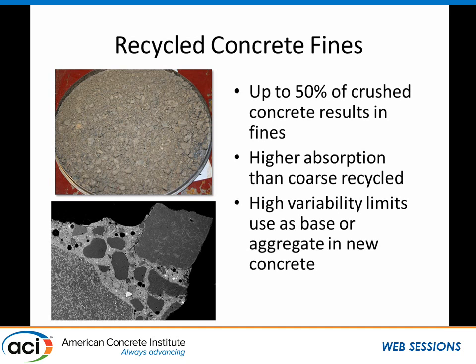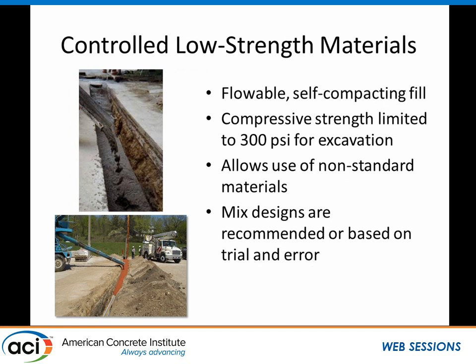roadways that are low criticality. We wanted to suggest something of higher value. Controlled low-strength materials represent an opportunity for us to add higher value to these kinds of waste materials, the fines that come from the crushing operation. And we think there's a lot of application for CLSM around the airport, particularly as the candidate of choice for backfill, flowable, self-compacting fill.